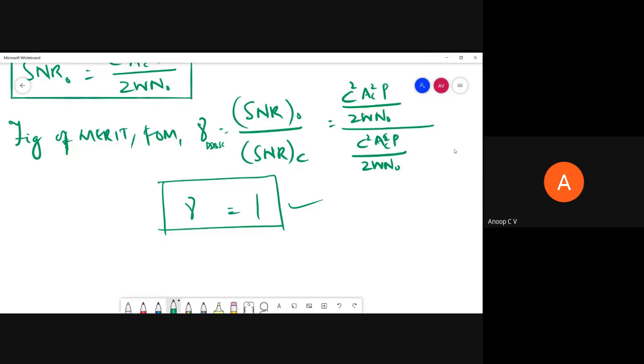What we got was an M of t term and a half Ni of t term. So we found that M of t and the in phase component of the filtered noise appear additively at the receiver output, and the quadrature phase component is completely eliminated. We mentioned that as one of the important advantages of coherent detection compared to other modes of detection.